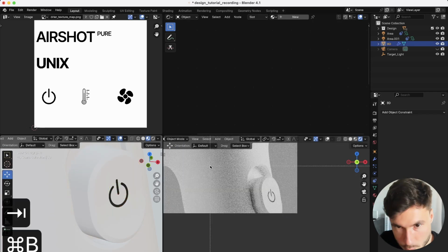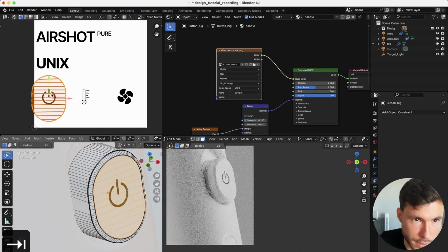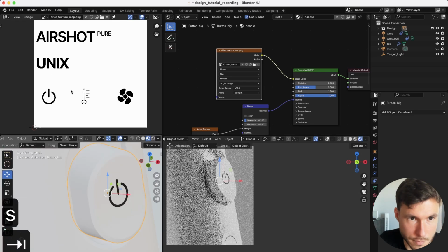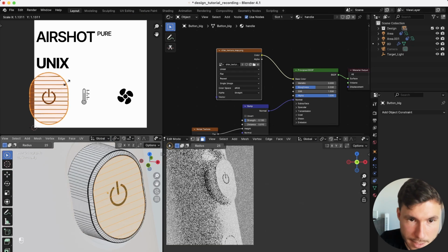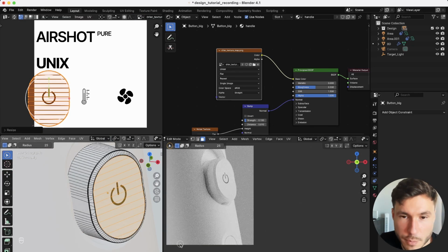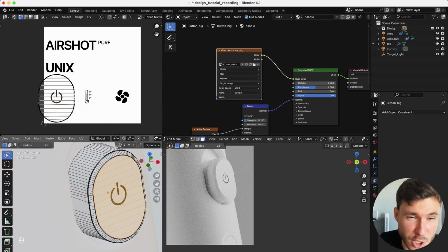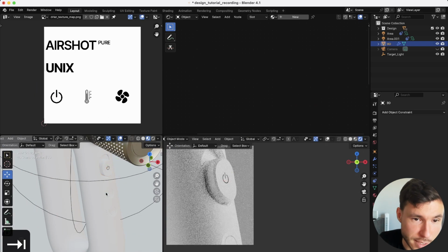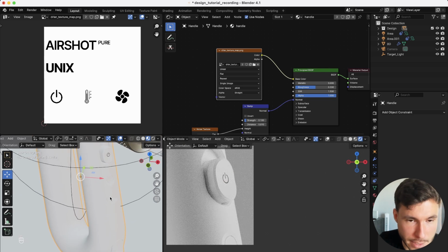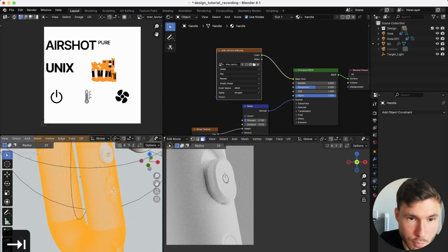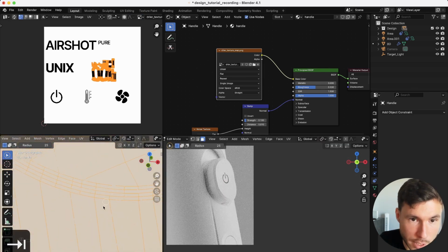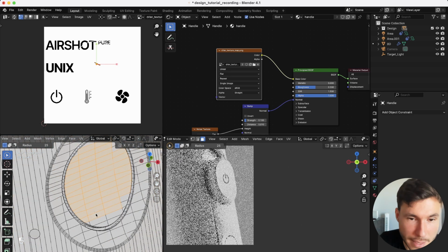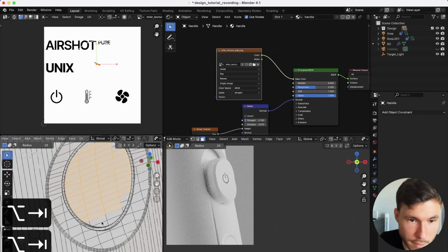And let me zoom in a little bit. Now you can again just adjust everything and bring it to the middle. And that's perfectly fine. Because this takes so long already, just do the same. Again, select this handle in object mode, press Tab, and only select this middle button. This will be with the fan blades, right?